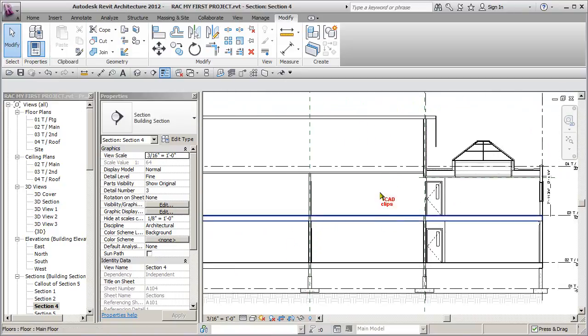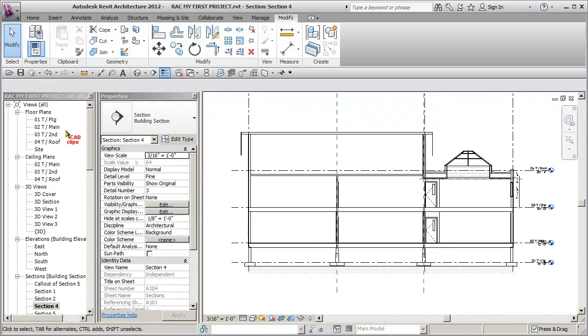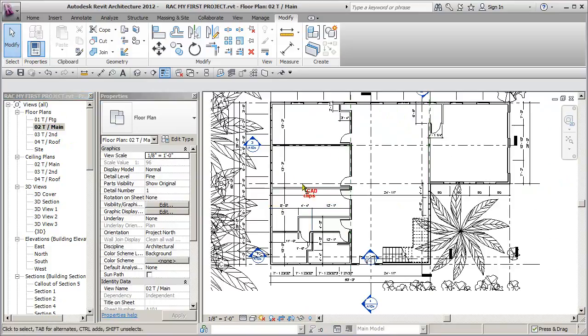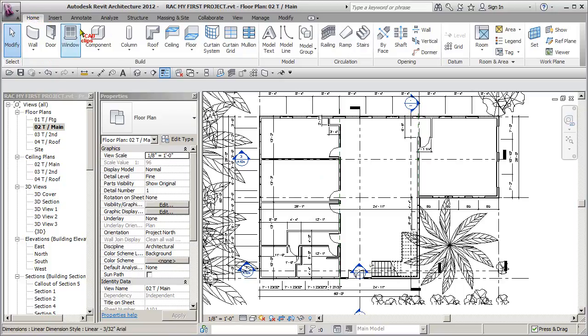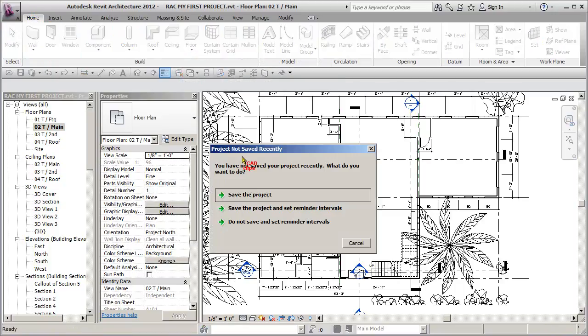All right, we've got our second floor ceilings. Let's go to our main floor and just have a look here. I think what we'll do here is we'll use the automatic ceiling tool instead, and maybe we'll go with just drywall instead of not even any furring or studs. So we'll go up at home and we say ceiling.